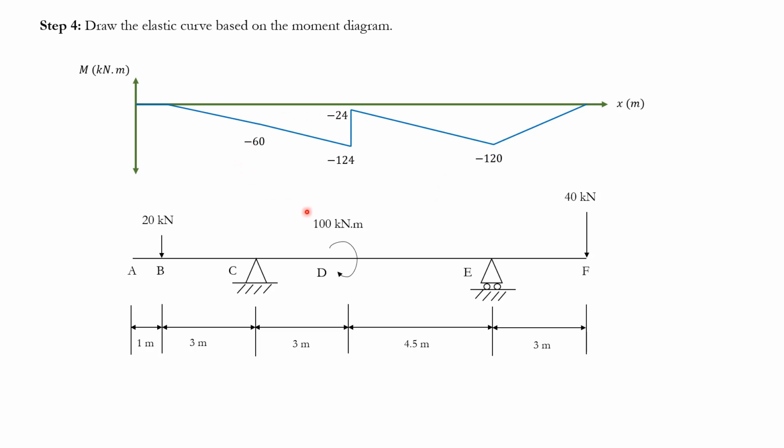So effectively, what that means is that from F to A, or actually let's not say A, because at A you would say, okay, wait a minute, this is 0. So let's just keep this for now. But from this point till this point, you have concave down. So you just have to draw an elastic curve like this from here to here. Maybe this is not drawn the best way, but again, it's going to be curved more a little bit here, maybe, right? That's more natural. And here again, it's going to be curved more. We can keep that in mind. Again, for the purpose of this question, it's good enough. But yeah, this is how it's going to look.